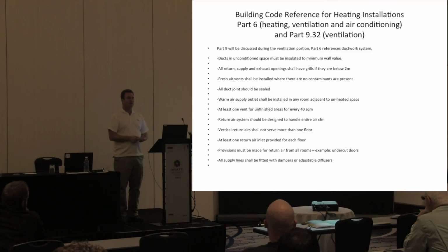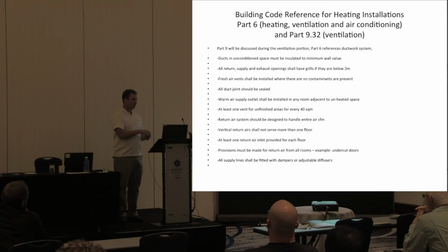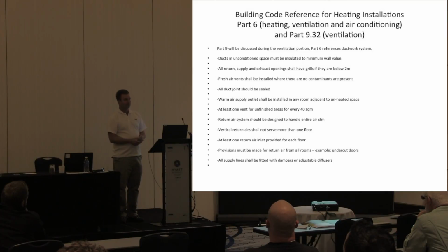I've been going to a lot of houses lately with super plush carpet, and it's great. The doors were undercut when the floor wasn't in, and then the carpet and the pad and everything else went in, and now the door is dragging on it. You have to have room for the air to go somewhere, otherwise you're just going to pressurize the room, and then it's not going to get any more heat or air conditioning if they have both.